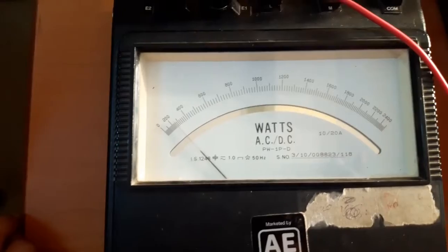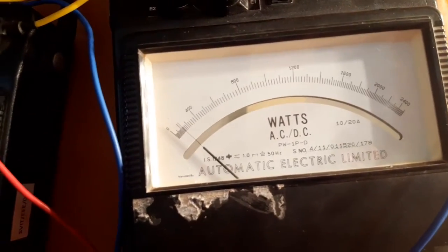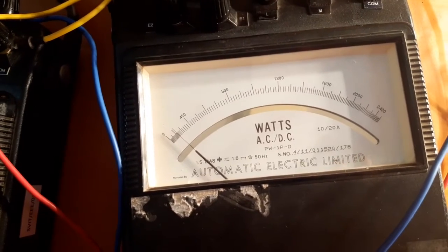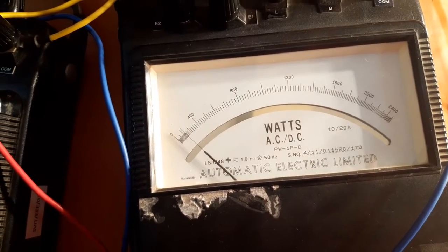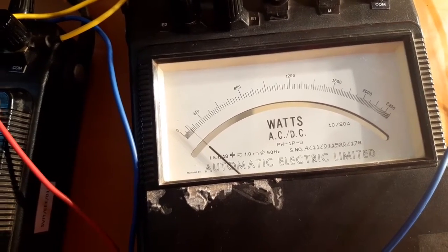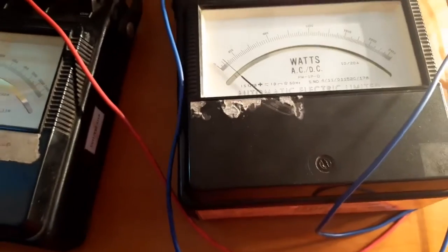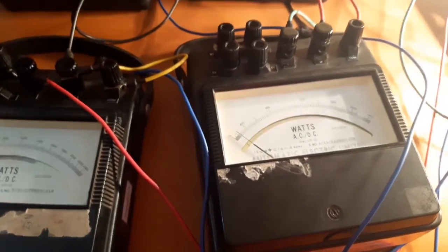The wattmeter 1 is displaying 260, and this number you have to multiply with the wattmeter constant 2, and wattmeter 2 is displaying 160. Again multiply it with the wattmeter constant 2 before you tabulate in your tabulation column. Now let us do the further calculations in the tabulation column. Let us switch off the circuit.